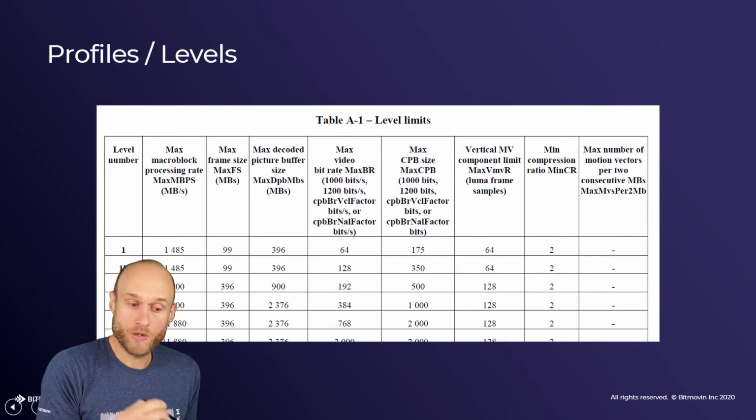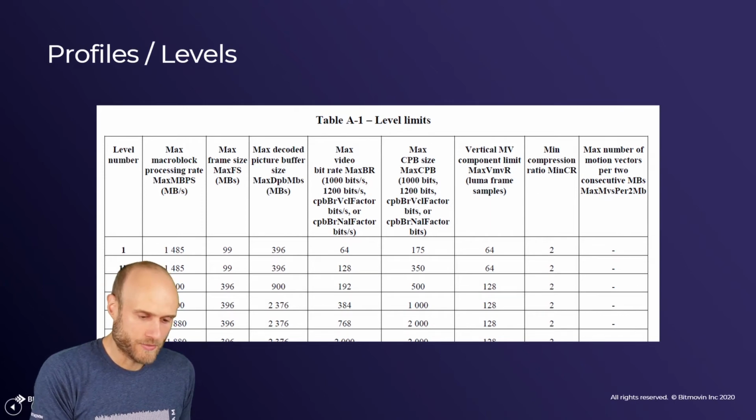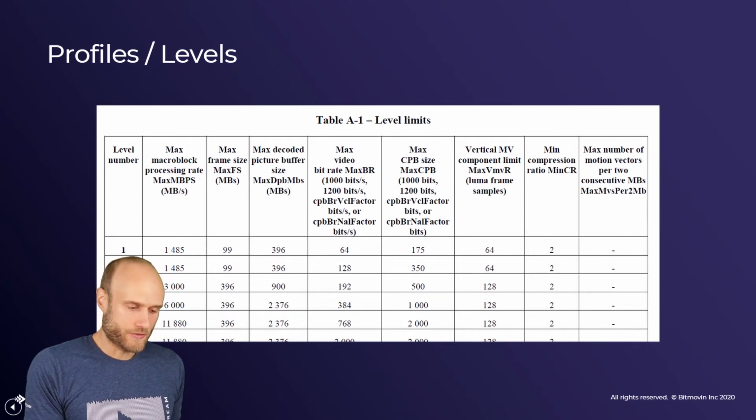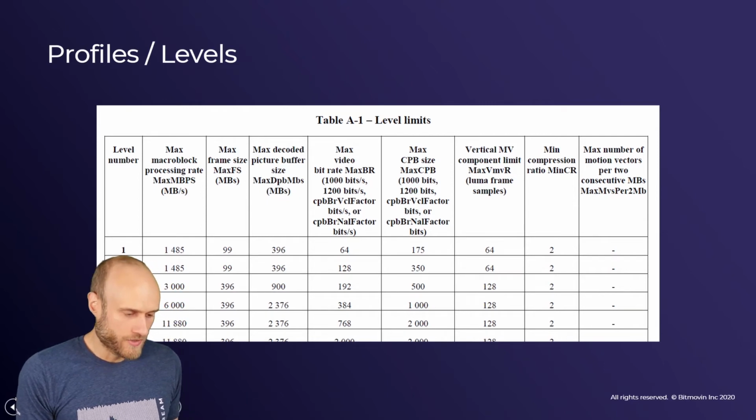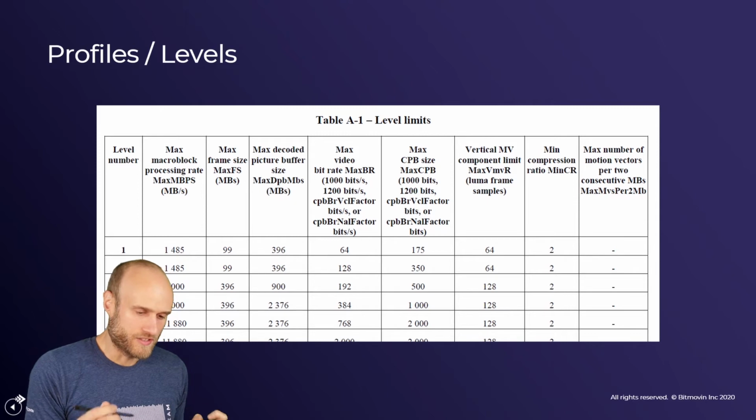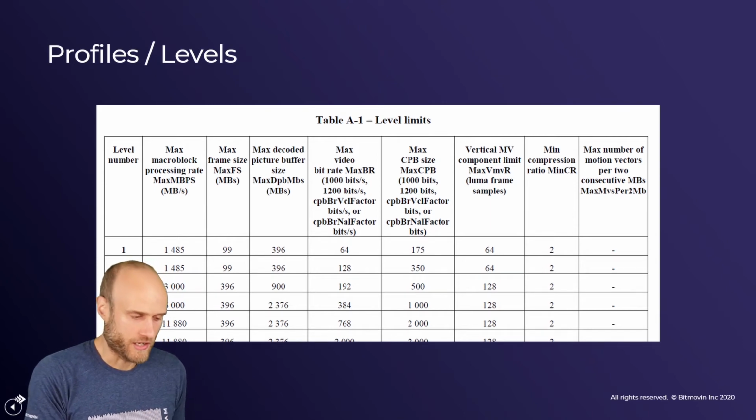On profiles and levels, or more levels in this case. As you might know, a level is a set of restrictions that you can set for a decoder in order to define how much a decoder can do physically. That's very important for hardware decoders specifically, because they are limited by what their hardware can actually do.